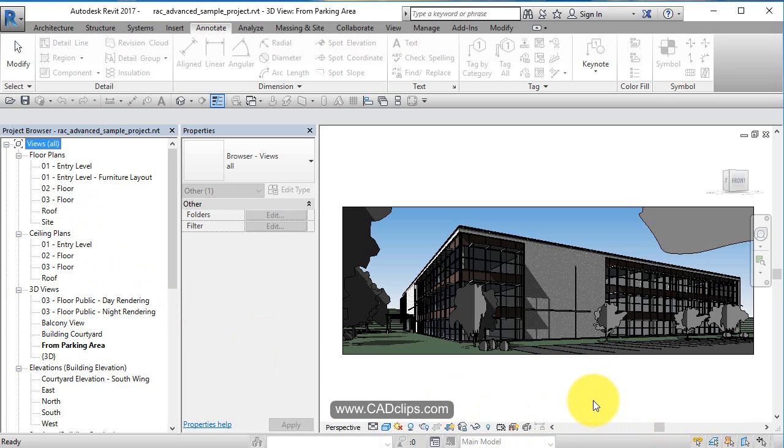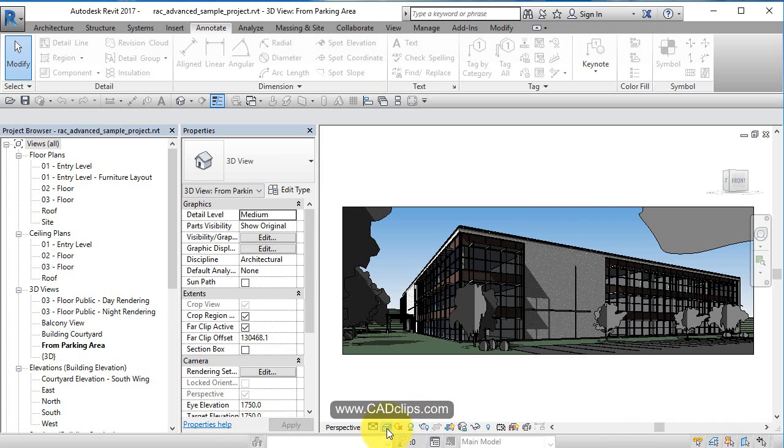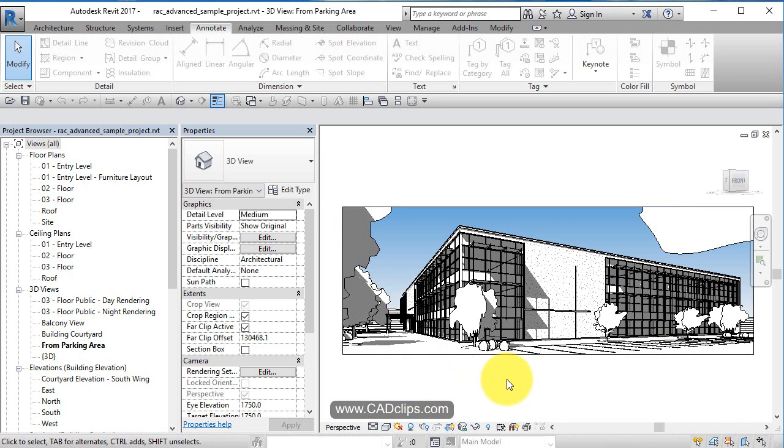This view you can see is shaded. It's not a rendered view because the trees aren't actually real, but it's close. It's got some shadows turned on and it's got the sky and stuff like that. So you can see in this particular view, we've got some display settings that are down in here. Some of these control our day-to-day work. If I click on here and say hidden line, it'll switch that display to be hidden line. That's just one of many settings that we can change.